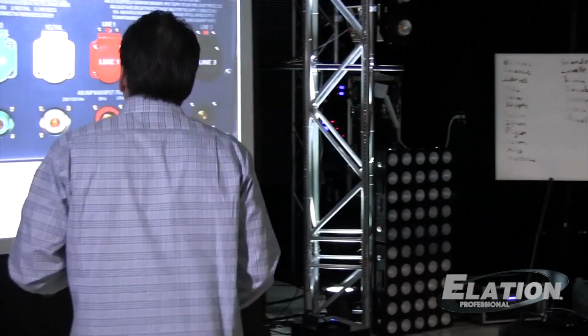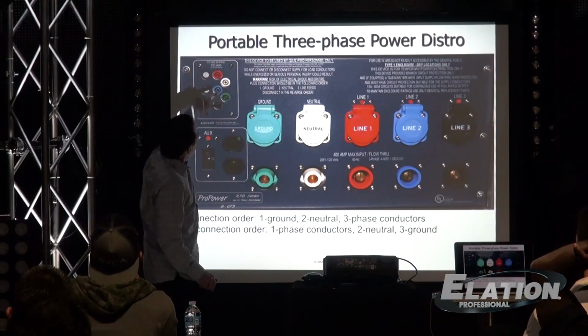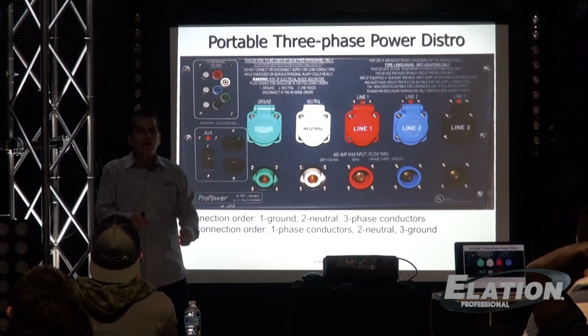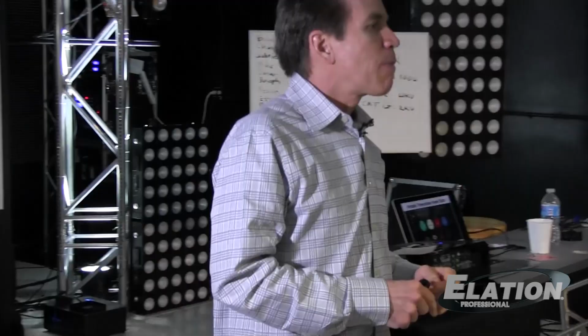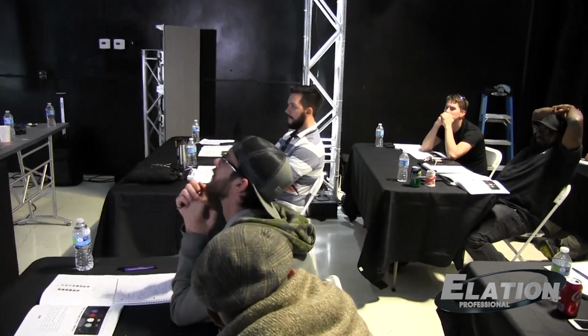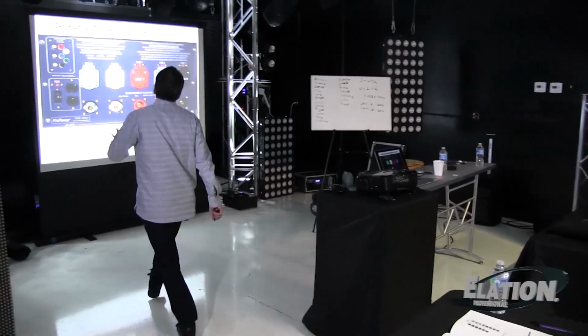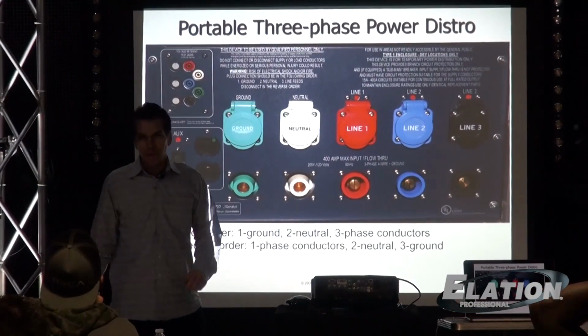While you're at it, you should also check for continuity between the neutral and the green ground. Make sure they're bonded together. Yeah, Kevin? Every time when you see a panel like that without neutral? Okay, so the question is, is there ever a time that you will see a panel like this without a neutral?